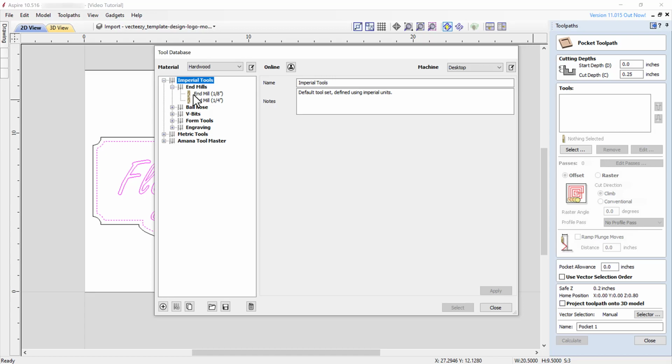In this particular case, since we have a significant amount of open space to clear, we might consider using a larger end mill to clear the open space quicker. We can then follow that up with a much smaller end mill with the size appropriate to cut out the material between and within the lettering.